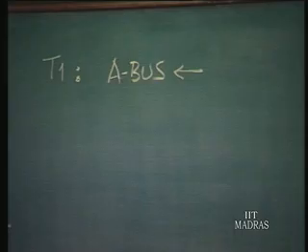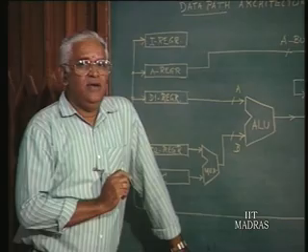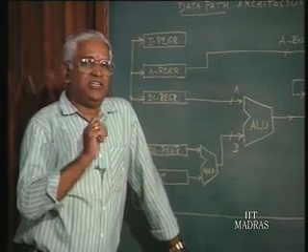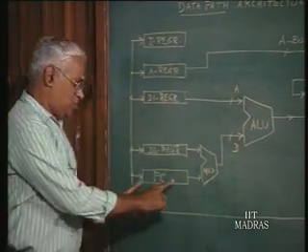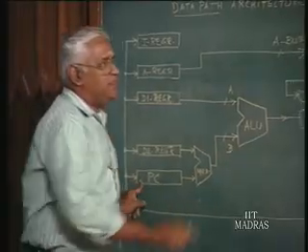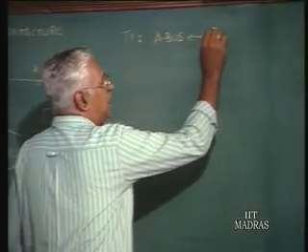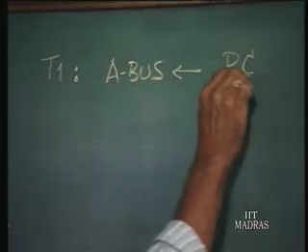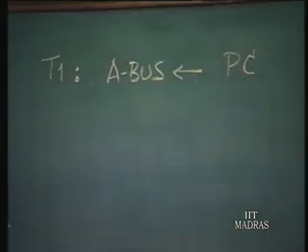We were in fact discussing instruction fetch, remember, in which case the instruction is pointed to by the program counter contents, so essentially in T1 it is the program counter contents which will be placed on the A bus.